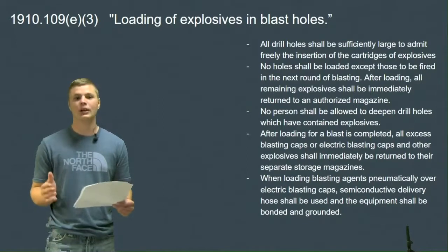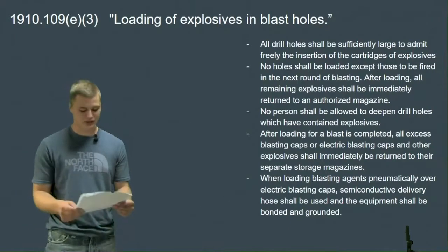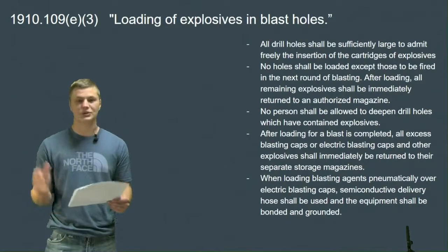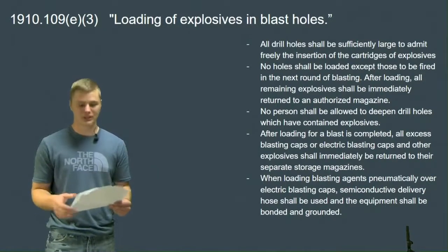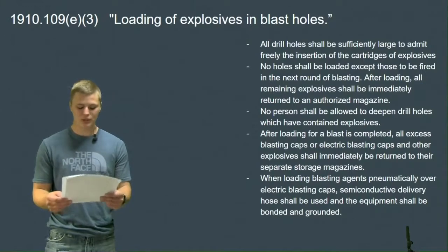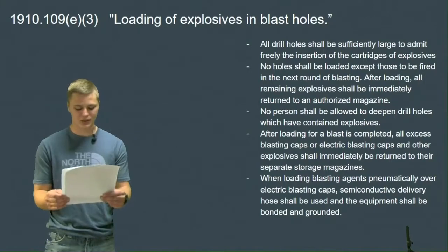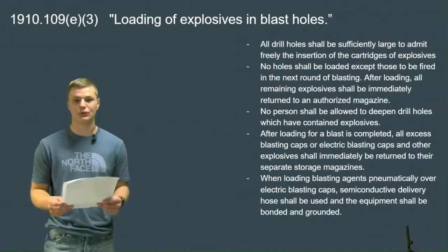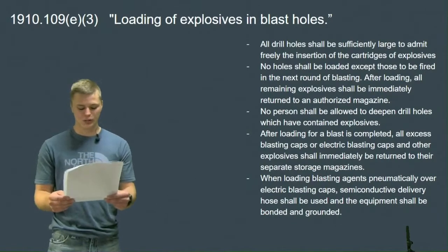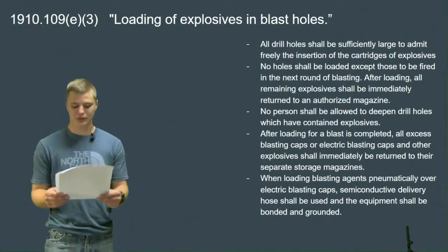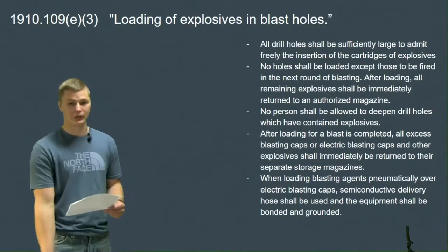As I said earlier, the explosives cannot be stored in the same place as the blasting caps and stuff like that. No person shall be allowed to deepen the drill holes in which the explosives will be contained. After loading for a blast is completed, all excess blasting caps or electric blasting caps and other explosives shall be immediately returned to separate storage magazines. When loading blasting agents pneumatically over electric blasting caps, semiconductive delivery hose shall be used and the equipment shall be bonded and grounded.